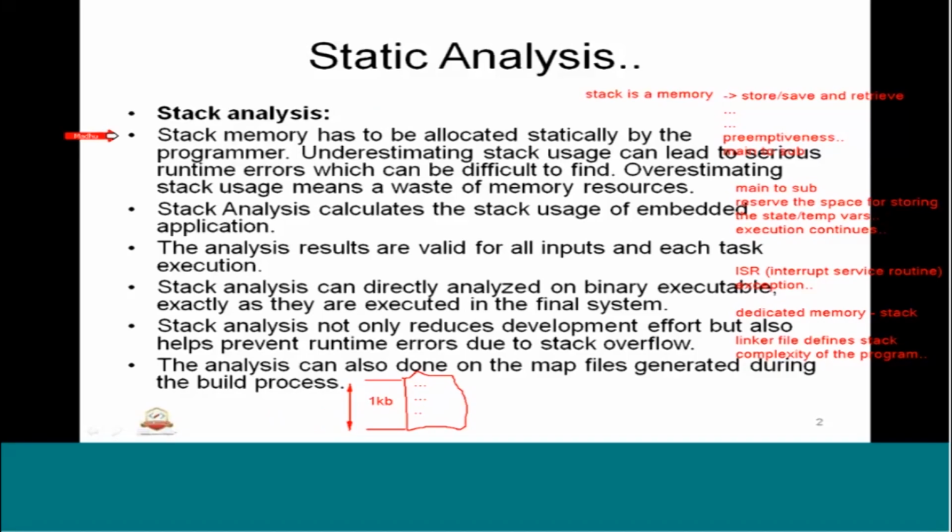So, stack analysis. Stack memory has to be allocated statically by the programmer, as I said, during compile time. Underestimating stack usage can lead to serious runtime errors, because we don't know the behavior of the program, since the stack memory has already overflown and it is not predictable. So definitely we need to have a buffer of the stack at any point of time during the program execution.